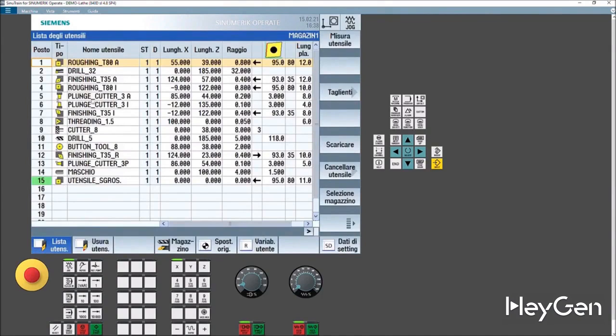Setting the insert angle to 55 auto-adjusts graphically. It shows 90 degrees. I set 80 and it displays a rhombic shape. Changing the tool holder moves the insert. It provides insert dimensions, spindle rotation, and coolant or high pressure options. These are machine-dependent features. To load new tools, a series of tools including special ones is available.